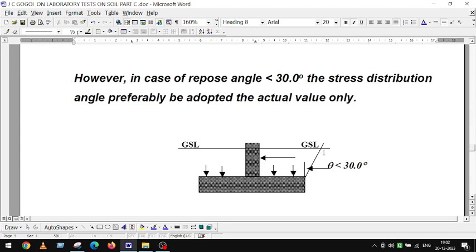If we go for 30-degree angle, this much of soil, same pattern, this 30-degree soil will be there. This area shall be resisting our upward tendency, uplift forces. In SBC analysis, we are also considering that some skin resistance shall be developed on all sides of the foundation, and that is also included as a resisting force. However, we are considering this as per our angle of repose.